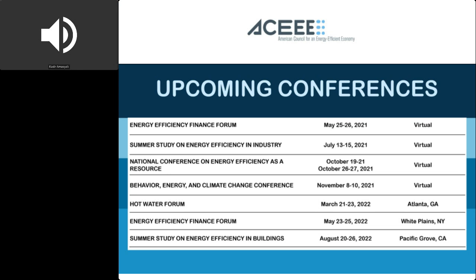We have DR commands. They can increase or decrease the deadband of the water heater. So if we send, for example, load up command, we can turn on the heater more frequently because we will have a narrower deadband, so it will be on and off more often. If we send a shed command, it will increase our deadband, and we will turn on and off our water heater less frequently. Got it. Yeah, thanks for that clarification.